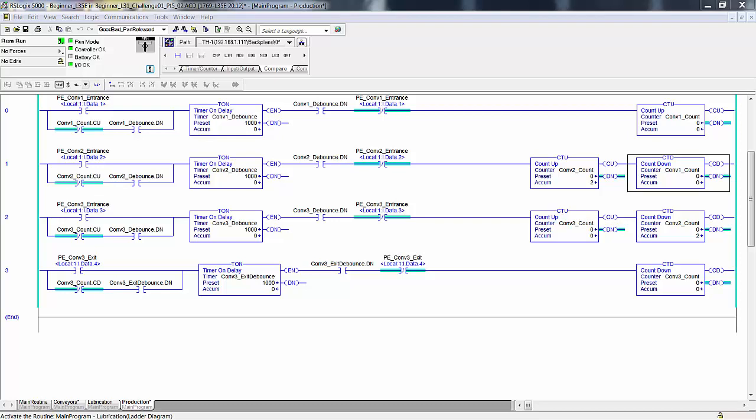In other words, we ran conveyor 1. So in the preceding step 6, if we went ahead and ran the conveyor, then the obvious conclusion is that those 3 cartons in step 6 are now going to hit the end, or I should say the entrance of conveyor 2. Carton arrives at the entrance to conveyor 2. Decision is to run the conveyors 1 and 2 or wait for logical conditions.